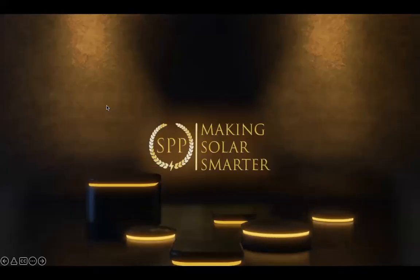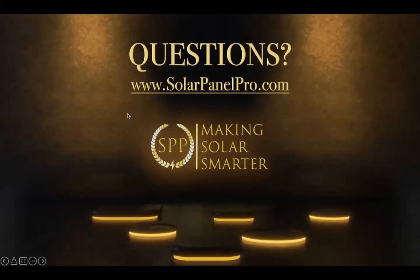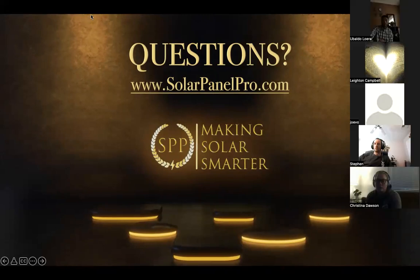Made some adjustments to the proposal this weekend. Shaded cells. Pretty simple stuff, right? The big thing to remember is that if one of the cells gets shaded out of the entire panel, it will drop production by up to 30 to 40%. It's a huge thing to note. So if you see shade on there, or if you see, well, I'm only producing 7,000 kilowatt hours on a 9 kilowatt system, it's because we've already accounted in the proposal for what the sun factor would be for shading on that panel.